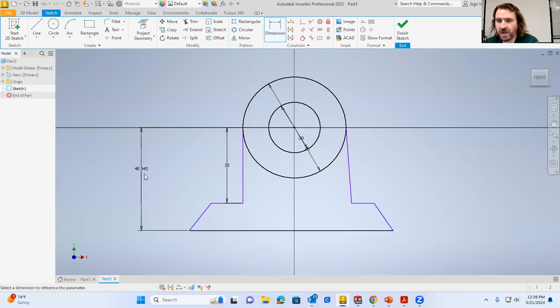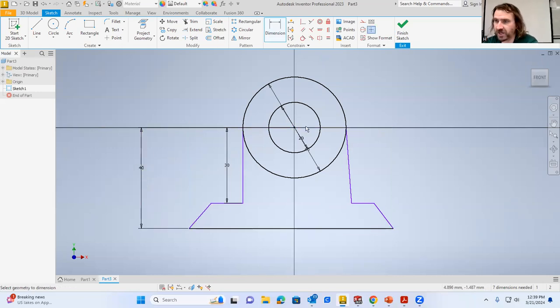and so it doesn't really matter one way or the other. If we draw this and start dimensioning, this line here is not a straight vertical line, so I'm going to use the constraint tool and make that a vertical line. So that's pretty good. Then I've got to make sure that we get this. This is 10. I'm looking at the dimensions that are given to me in the drawing itself. This is also 10.